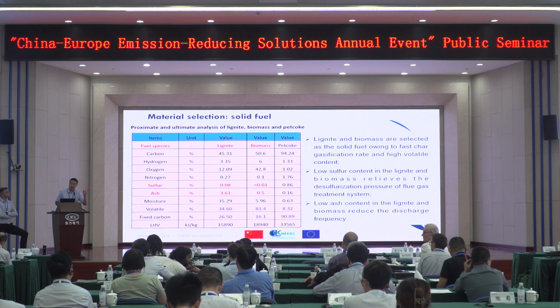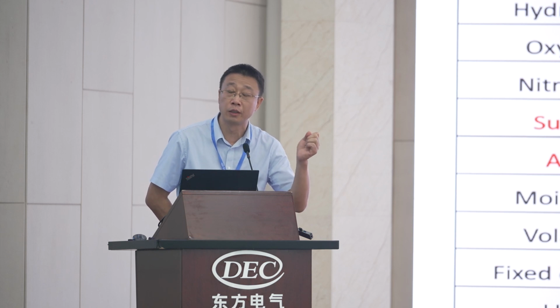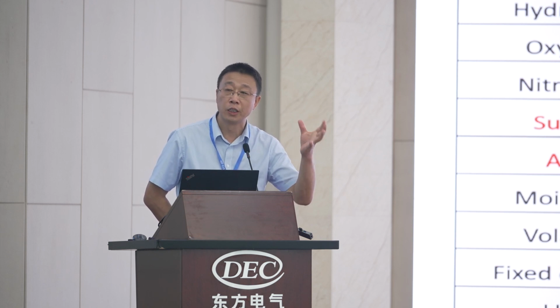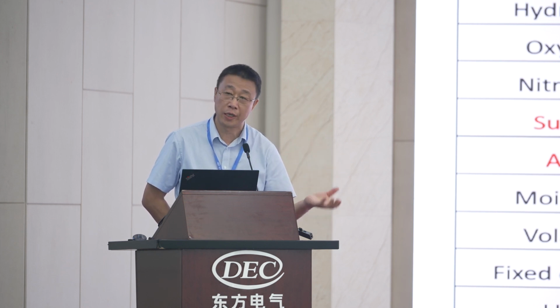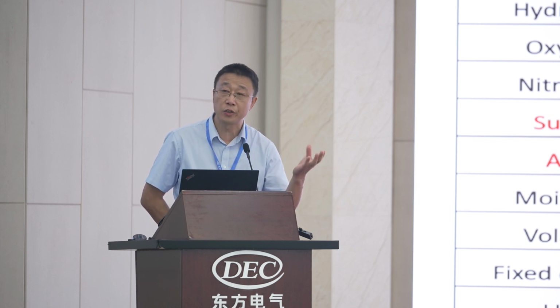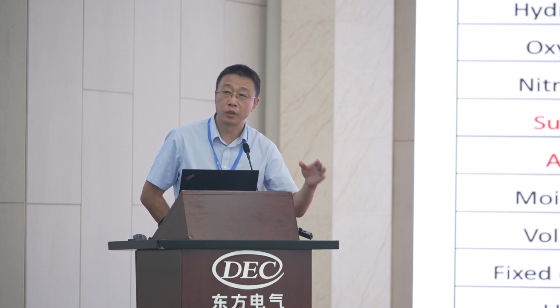If we feed the ilmenite particle larger, for example 3 or 4 millimeter, there is some possibility for very big particles to be located at the bottom area of the fuel reactor. In this case, we will discharge the very large particles from the reactor bottom.